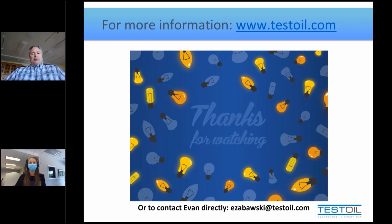But no, you don't need to sample all 3. They're all sharing the lubricant. The analysis is not that detailed to be able to tell you bearing wear from the electric motor compared to the gearbox compared to the pump when you have shared lubrication systems. So we just monitor it as a whole through that one primary location. And you can consider, like I said, if you wanted a backup sample point at the return lines of each individual machine, so that you could try and isolate which one in particular is causing the problems if the primary ever showed you a problem.